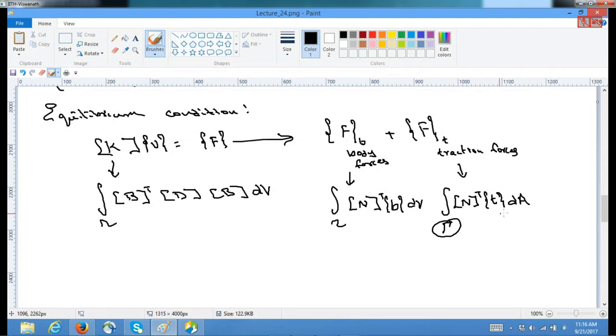And since we know our shape functions and the gradient of shape functions, which is related by the strain displacement matrix B, and if you know your constitutive relation D, then we can obtain our K matrix and the nodal force vector. Then we carry out the assembly, impose the kinematic boundary conditions and condense the global K to determine the unknown degrees of freedom, and that's how we solve the problem, just as we have seen